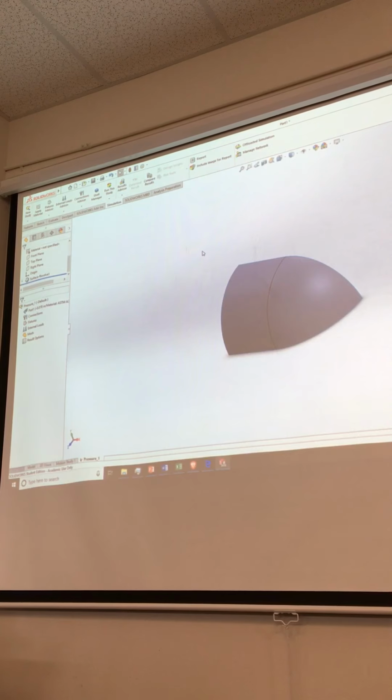Well, we have to do symmetry boundary conditions on this, right? This part is symmetrical, the way we've modeled it is symmetrical, and I insist you model it symmetrical because I'm a mean instructor. Okay, so we have to do symmetry boundary conditions on these, and that means we're going to have to put boundary conditions on the 3 symmetrical borders. Okay, and one of the parts of this exercise is what are symmetrical boundary conditions, what do they look like?